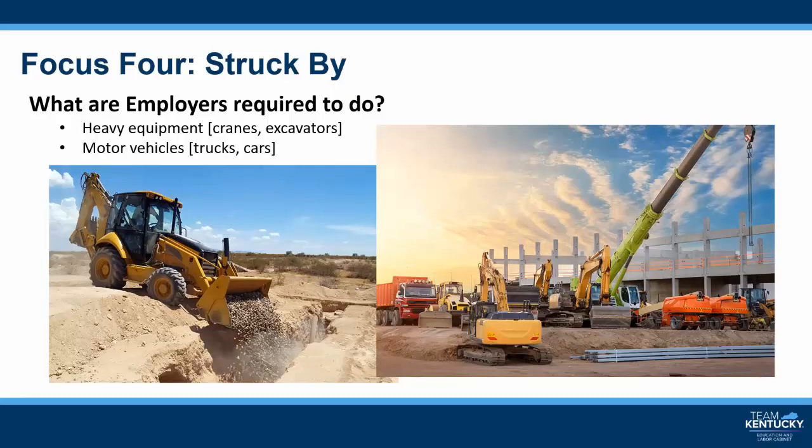They also need to ensure that roadways and grades are maintained to accommodate the safe movement of equipment and vehicles. They must also ensure that all earth-moving or compacting equipment with an obstructed view does not operate in reverse gear unless the equipment has a reverse signal alarm or a worker has been designated to signal when it's safe.